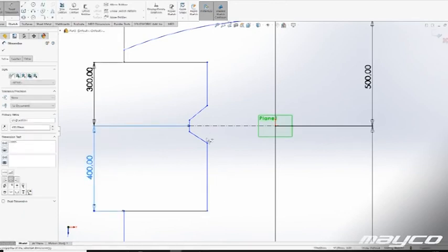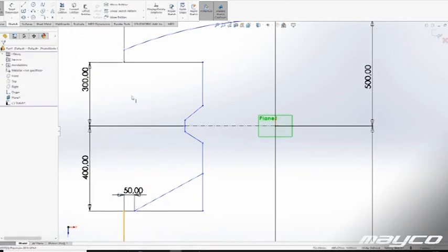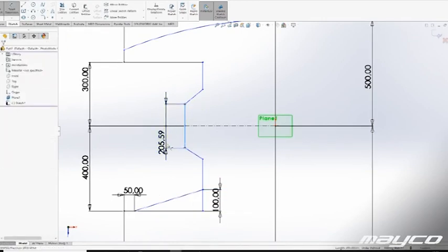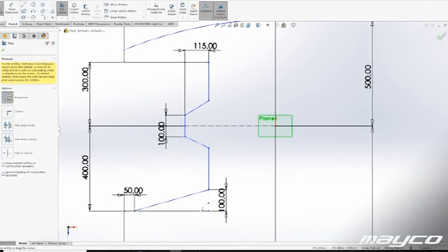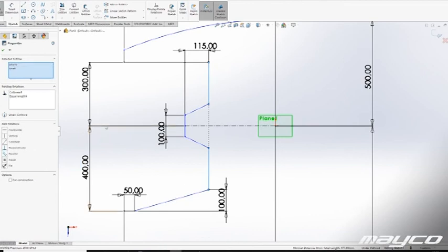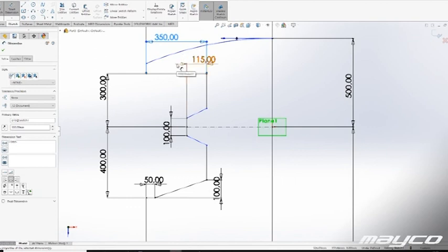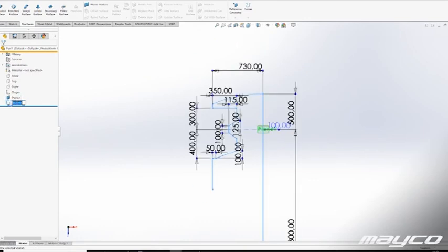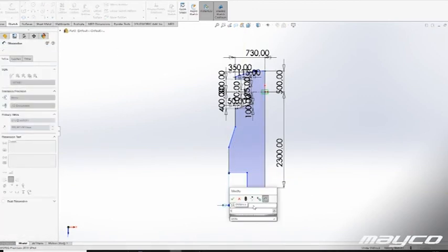If you are designing a car, it'll take you 3, 4, 5 steps to really get the shape that you want, especially with what I'm doing, where you have to look at regulations, for example. Your light might not be high enough, or it might not be far enough to the outside, or whatever, so you need to redesign, or you might have your hips too thick and the seats won't fit, so you have to make the interior space wider and still keep the look you're going for. So it's a back and forth several times, and with that back and forth you also learn more and more how to model what you want.